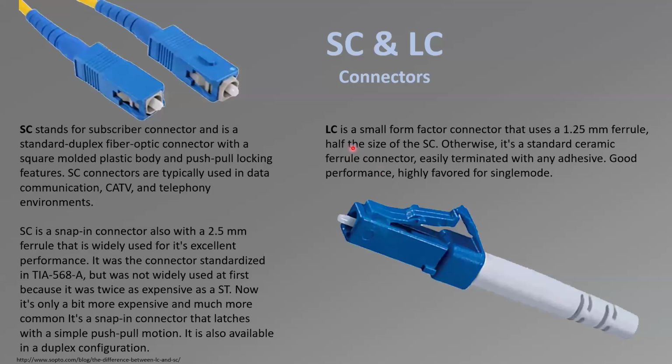Now, later on, the LC connector was developed. It serves the same purpose, except, well, what did we write here? LC is a small form factor connector that uses a 1.25 instead of 2.5 millimeter ferrule. Here's the ferrule, half the size of the SC. Here's the key component, half the size of that. And it's a standard ceramic ferrule.